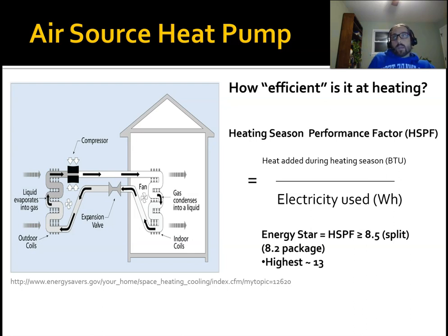That is because if you think about indoor air temperature, let's say you have a base temperature of 65. In a really hot climate, maybe you're at 100 degrees, so 100 minus 65 gives a 35-degree delta. Now think of a really cold place like northern Alaska or northern Canada, where you might have minus 20 and want to get it up to 65. That's a huge delta, about 85. That's why, generally speaking, HSPF ratings are lower: you're under conditions where it's harder to grab heat from the outside.